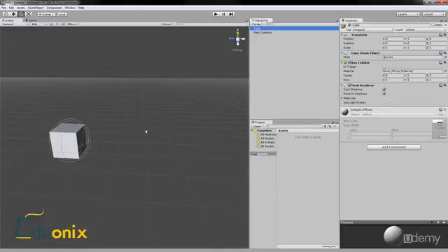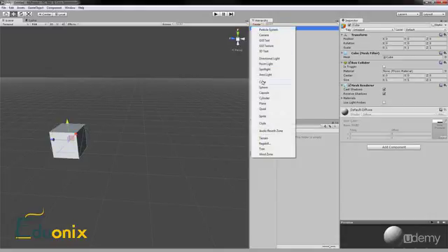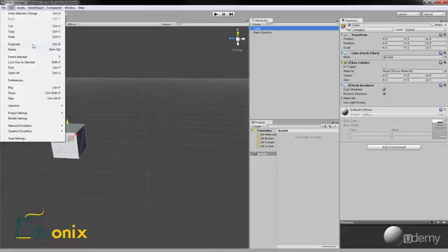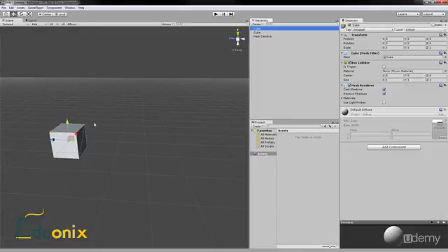So what we're going to do is we're going to make a wall. So we have our cube, and we would like another cube. You can go down, create another cube if you'd like, or you can duplicate the current cube by going to Edit, Duplicate, or using this hotkey which you see right here, Control D, or Command D on a Mac. Once you duplicate a cube, it's obviously in the same position as the other one, so we can move it away from our other cube using the translate arrows.